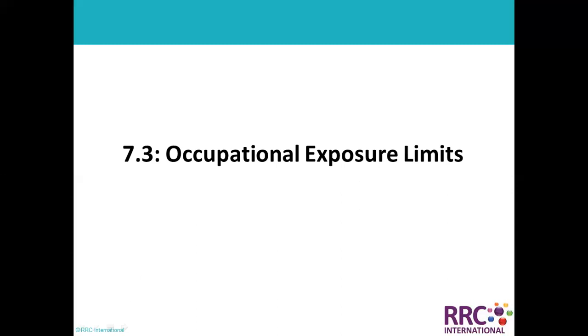Okay, excellent. So LEL should be 0%. LEL must be 0% all the time while you're performing hot work. That is why sometimes we have continuous gas monitoring, and we have a better ventilation or extraction system. We also make sure, before we start our project, that we isolate all sorts of energies, could be electrical, mechanical, gravity, motion, pressure, or any toxic hazardous substances, including H2S or any liquid coming to that confined space.